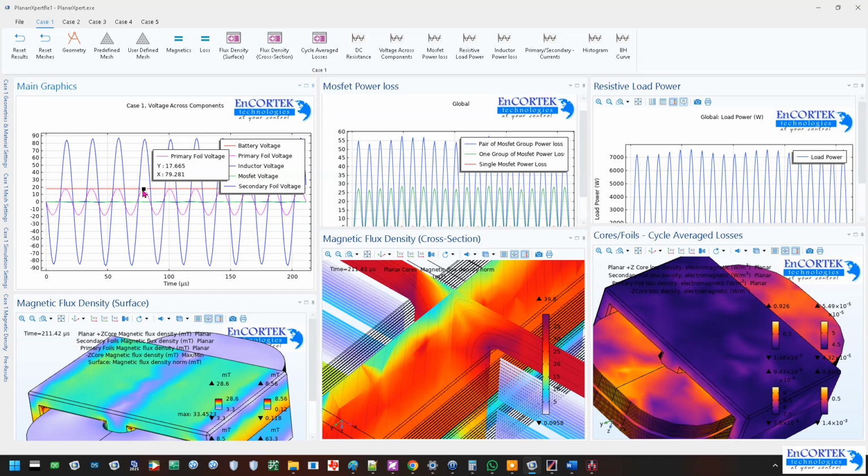So we're seeing the primary voltage coming in here. The transformer for a square wave itself, but a sine wave is easier to simulate. The square wave is a lot of load, computational load, I mean, right? So we have the inductor here, on a small scale. If we see the inductor and the MOSFET voltage, they are pretty much close to the transformer voltage. We know that we're going to have lots of losses, so there is a scale factor here. So we could pretty much eyeball this and realize, okay, this looks good.